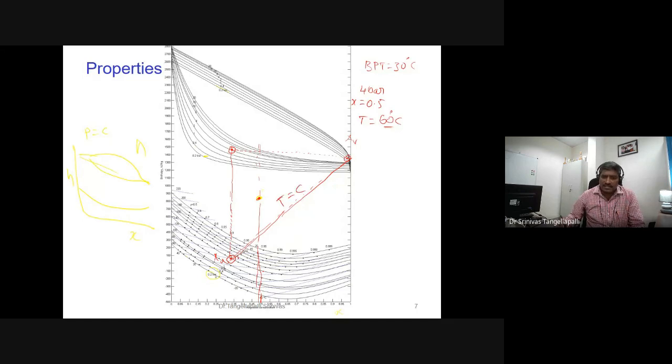Temperature is constant. This is the temperature of liquid, and this is the temperature of vapor, and this is the state where the 0.5 concentration line and the isotherm meet. This is your state, the liquid and vapor state. To identify this point, we start from the saturated liquid and end with the saturated vapor via the auxiliary point. Now, in the graphical method, XL can be read directly.